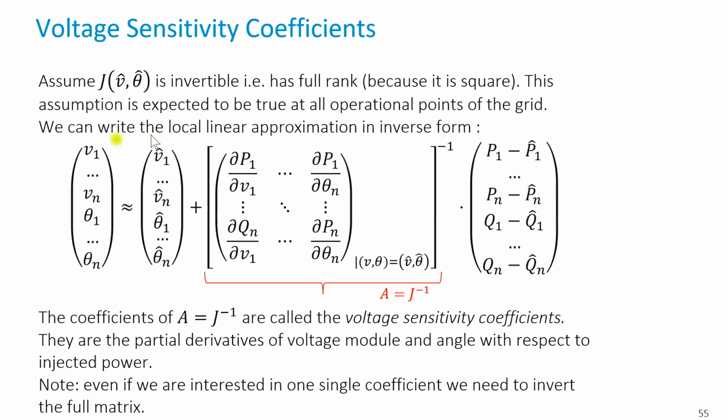Then we can linearize the problem by saying, I will control the voltage in my grid by transforming my power injections. For example, if I have a lot of solar panel injections, I may consume more in a battery, or I can also inject or consume reactive power to mitigate the voltage problem. How can you consume or inject reactive power?